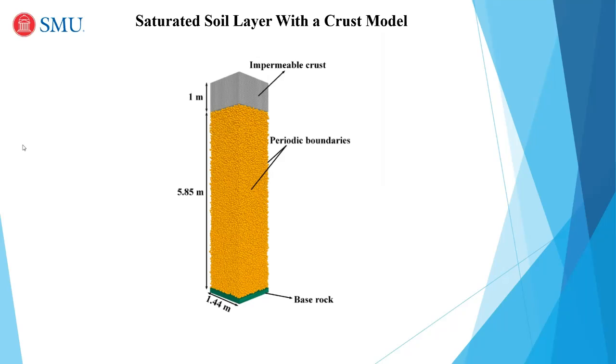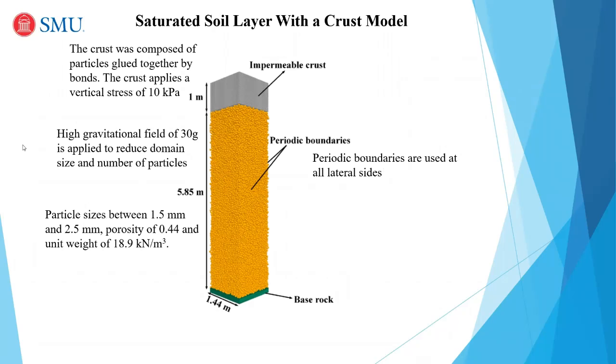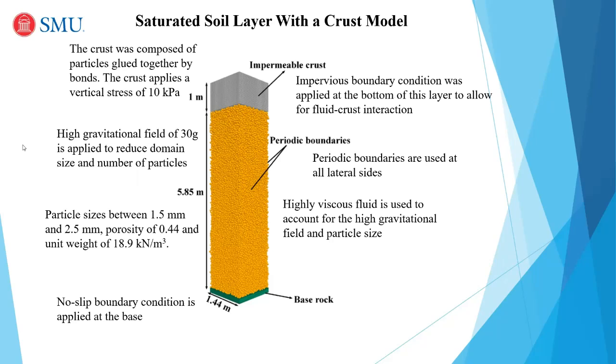But the soil underneath is liquefiable, and its water is trapped inside this column and cannot get out anywhere. So pretty much the same data, except we added this crust that is imposing a stress of 10 kilopascal on top. We carry out the simulation.